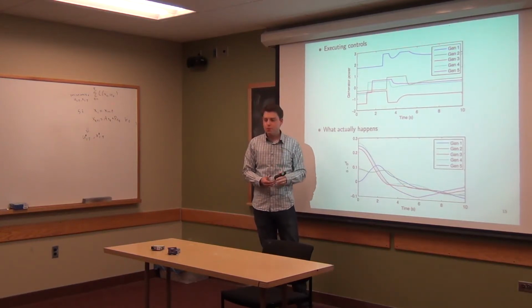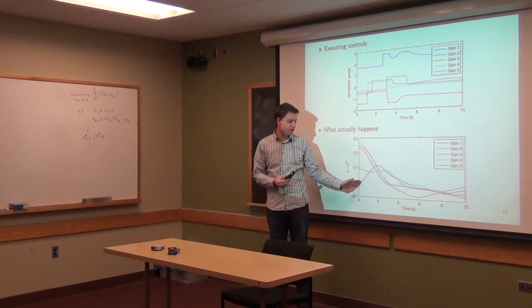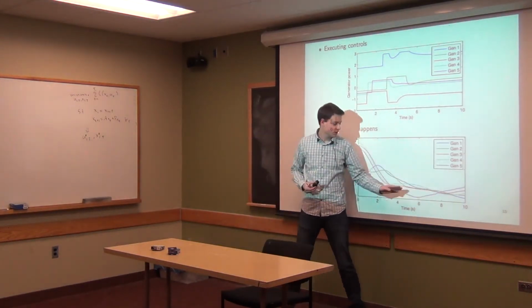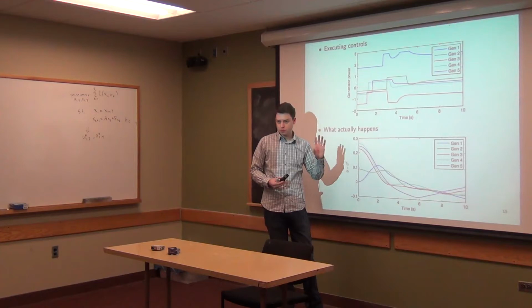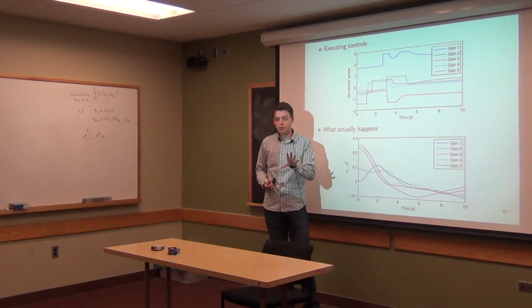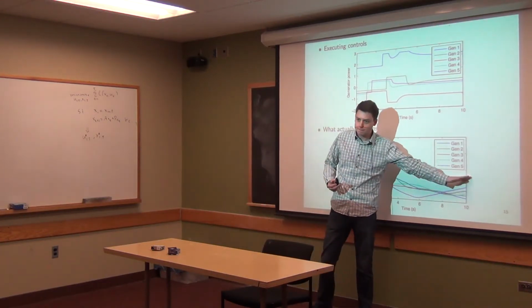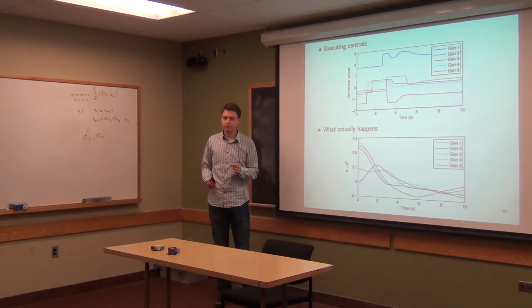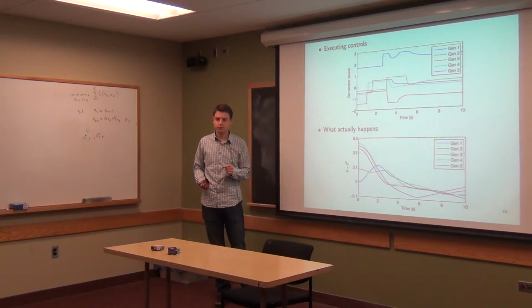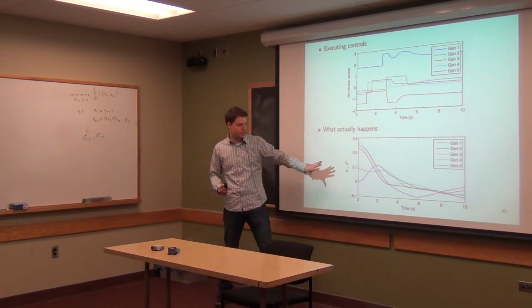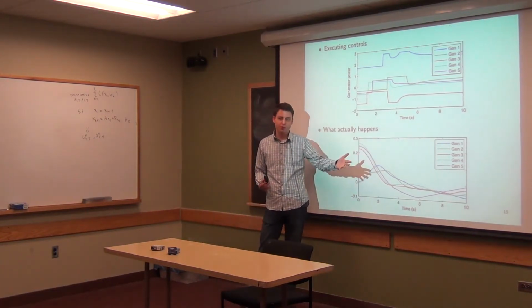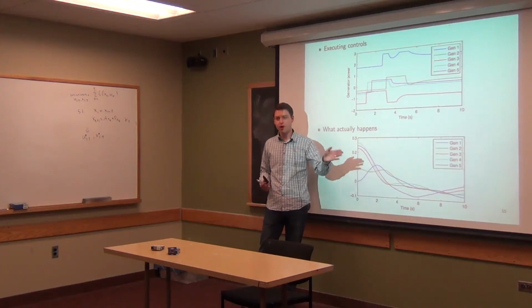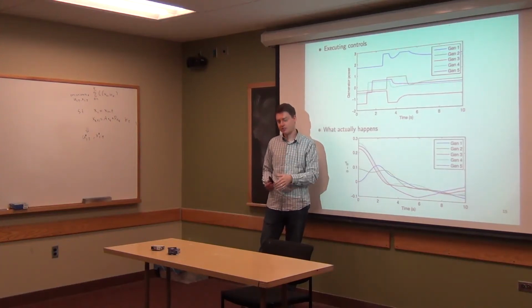So all we do is we say, okay, this was good for the first time, and it got kind of bad out here. We take our optimization problem, we optimize over the whole part here, but then we only take the first action we get back. Right? And then we see what happens. We repeat the process. Rerun the optimization problem, see what the first action is, and take that action.